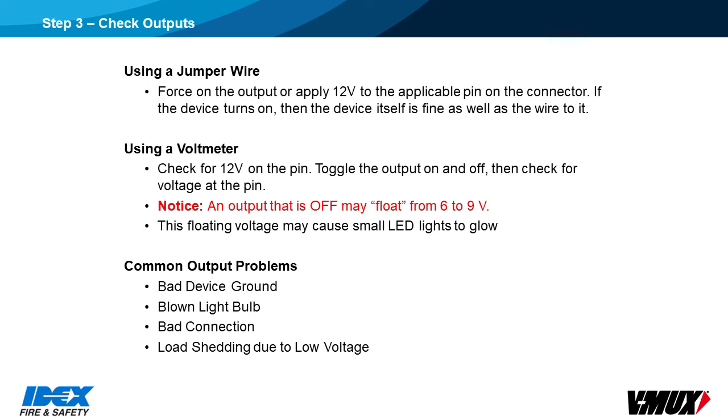The output might also be off for a diagnostics fault. If output current exceeds its designated current rating, the output will automatically turn off. The module will attempt to connect the output to the load 2 more times at 5 second intervals. If the output is still overloaded, then it will remain off.